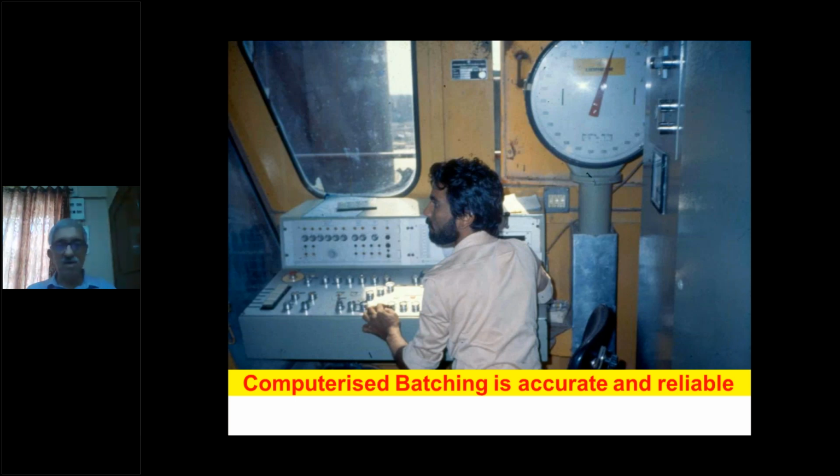He may press a button too long and excess material can go into the weighing area, or he may press a button too little and thereby cause less material to go in. So it was always preferred in our experience, when this batching plant functioned for the first time on the Tata Electric Unit number 5 project, that it is good for quality, good for strength and durability, good for your statistical data if you run the plant in either semi-automatic or fully automatic mode.